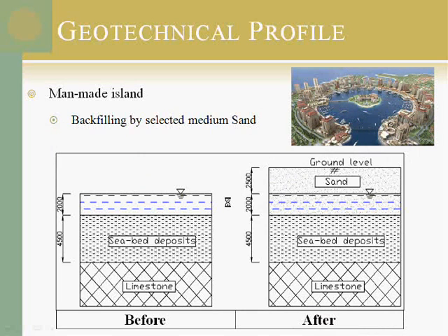As a start, you can see that this is a man-made island, and it was exactly as it's shown in the before left picture. As you can see, they filled that water by the sand for around 4.5 meter, before the backfilling of the soil. It was a seabed deposit, so to reach the rock for this layer was around 9 meter in the sand to support your foundation, and this will be discussed in the foundation part.